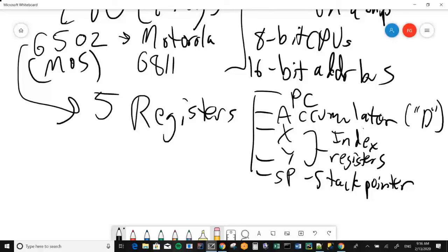And so what happens is, in a high-level language, you give it an API that lets you specify all that. But that API is ultimately compiled down to machine-level instructions that are just storing values in these memory-mapped registers. What's great about the API is that when you're programming in a high-level language, you don't actually have to know where in memory you're doing these updates, which is good. And you also don't have to know what specific bit patterns to store in memory to get those updates to happen the way you want them to happen.